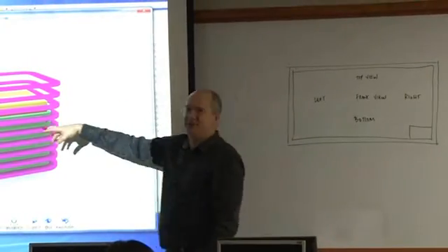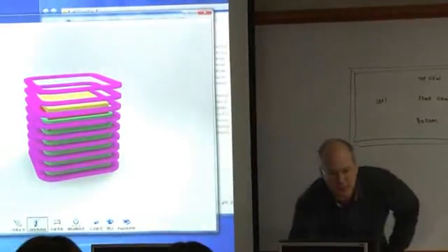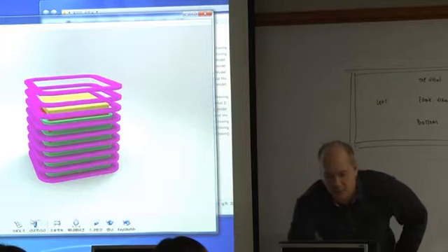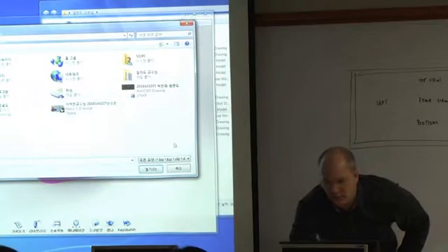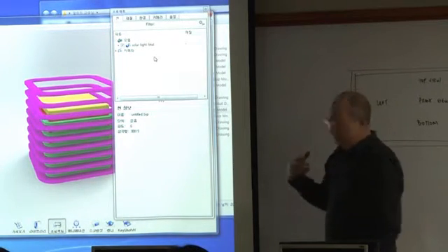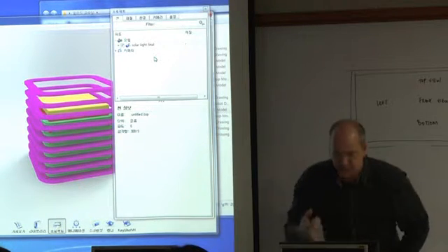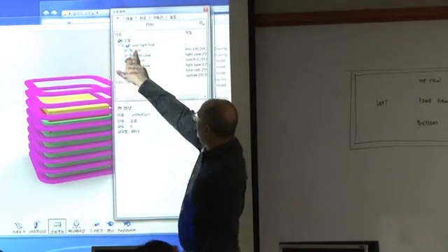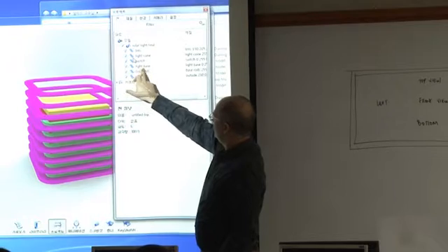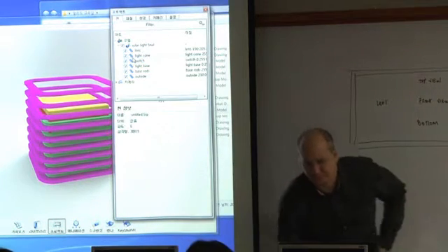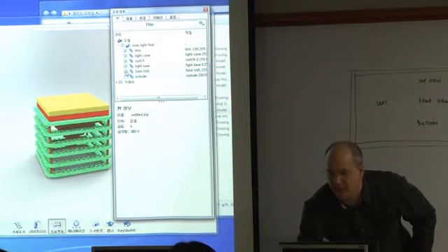So let's go into what's called the library. And here are all your material choices that you can assign, okay? Cloth, leather, liquids, metal, okay? That's your materials library. Over here, we can import other models, okay? Now here, we got all of our information on the data model here, okay? So we've got the lens, the light cone, the switch, the light base, all these different layers were imported and kept separate in KeyShot. So we can turn things off inside of KeyShot and render individually, okay?